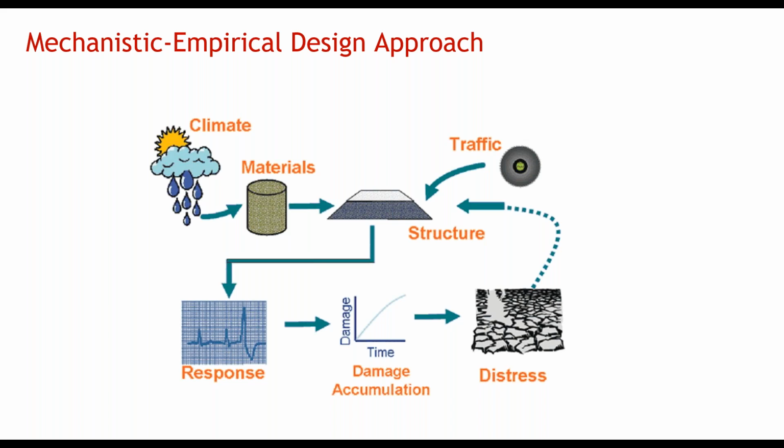Once these are tied together with the proper transfer functions, we have a much more robust view of how to design a pavement and how it will behave over its design life than we would based only on a statistical or probabilistic model that is based on empirical testing alone. Mechanistic empirical design is now included in the AASHTO Pavement ME software, which is readily available and used by several states. The methodology continues to evolve as more pavement performance information is incorporated.